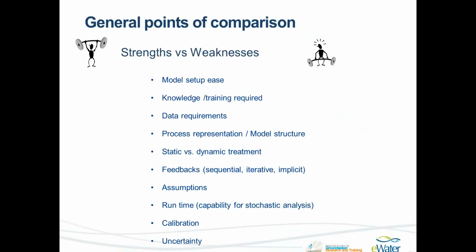So in the work I've been doing, there are some broad points of comparison with some quite subjective things and some other more rigorous and informative comparisons. Just to give you an idea of what I've looked at: how easy it is to set up the model. With Source, we have a GUI, and it's fairly nice, and it's a lot easier than, for example, using something like MODFLOW or HydroGeoSphere, where you are required to write text files to set up your model, and you're having to deal with perhaps more complex data sets.